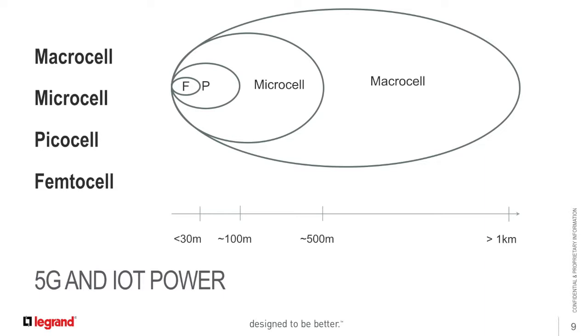Why do I bring that up? Well, with 5G radio, the free air propagation at 30 meters means that something inside this room radiating a signal will completely attenuate by the time it leaves the room, just passing through the air. So its propagation distance is very short.